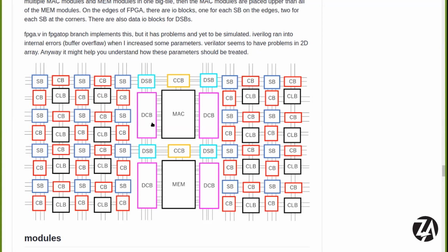For example, a 1-bit wide read-write instead of the usual 8-bit, because the output could be coming from a 1 LUT, for example. Anyway, long story short, we just had to drop that too. But once OpenRAM is ready, our control logic is ready, and we can put that in. And we think size-wise that will easily fit. So what you're about to see is only these CLB tiles that are hardened as one single block.